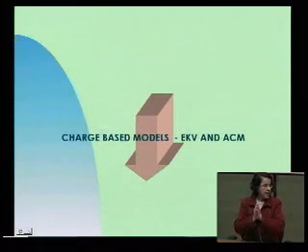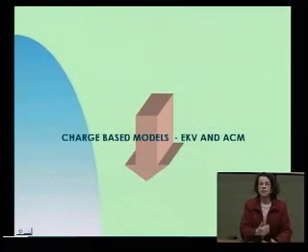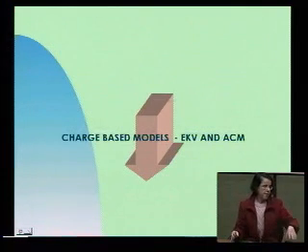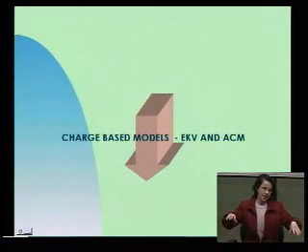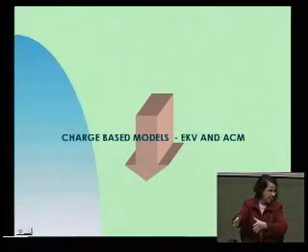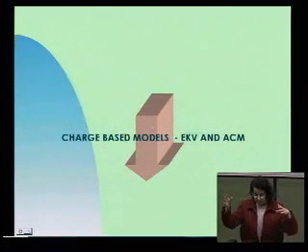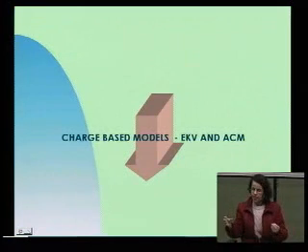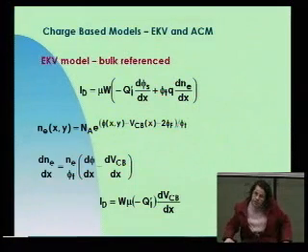That is, they have a single equation for each large signal or small signal characteristic for the whole inversion regime. Okay? They surely have the asymptotical behaviors like this exponential and second order polynomial, but they use a single equation for everything. Let's begin with the EKV model.